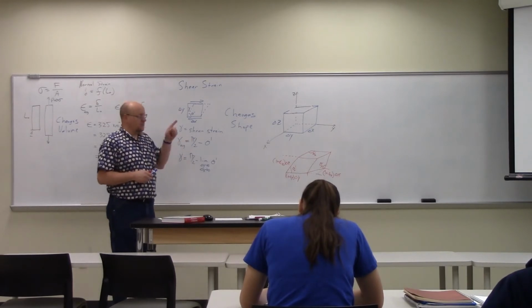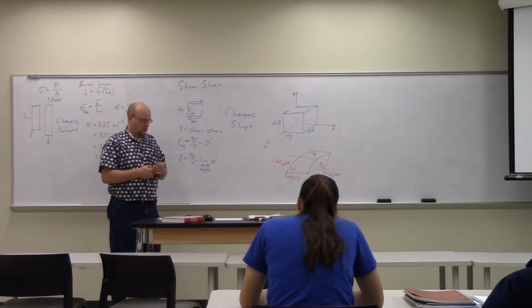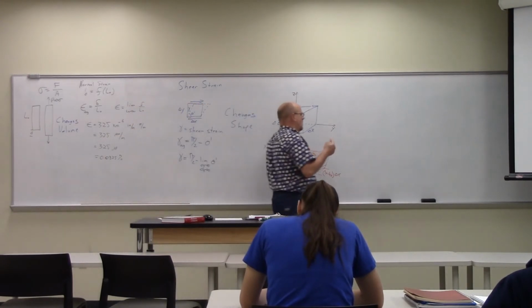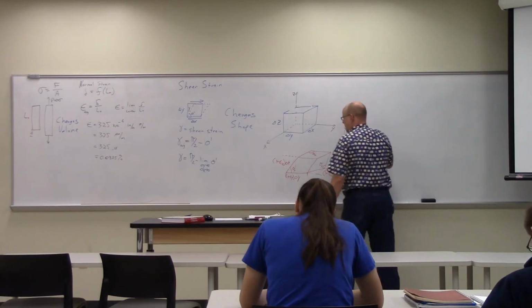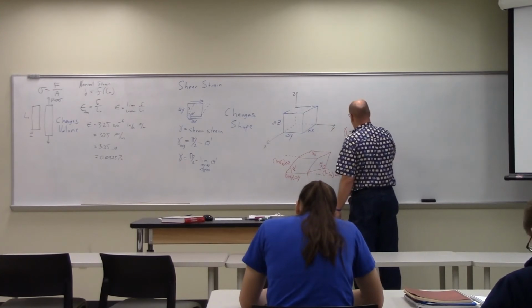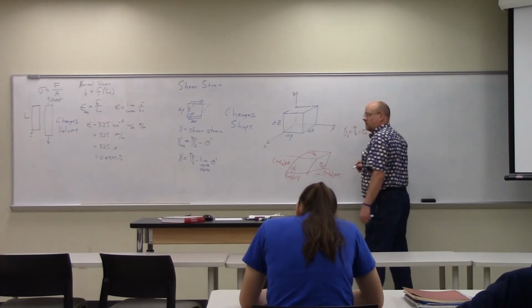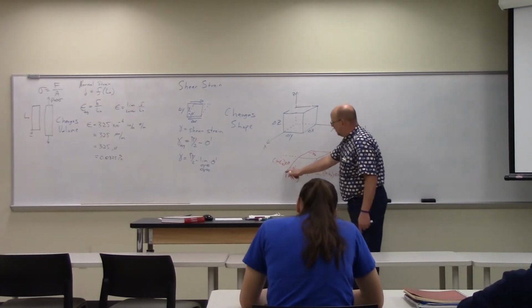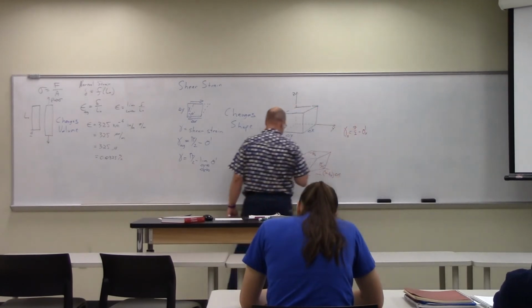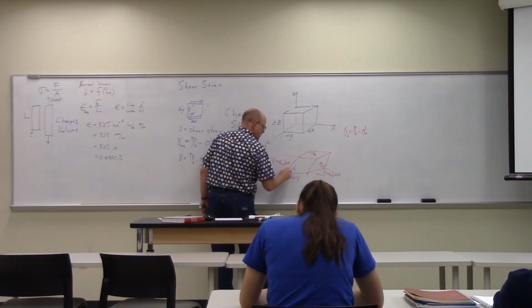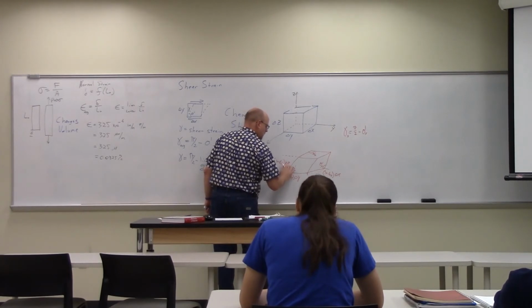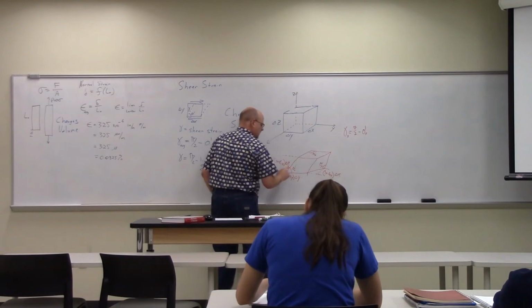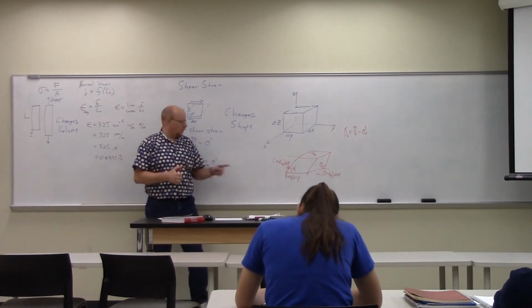Because theta prime x is not 90 degrees, we know that gamma about the x-axis is equal to pi over 2 minus theta prime about the x-axis. So this little angle in here, if I were to draw, that's gamma sub x, right? The shear strain at that little angle in there.